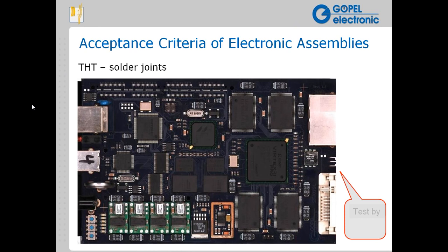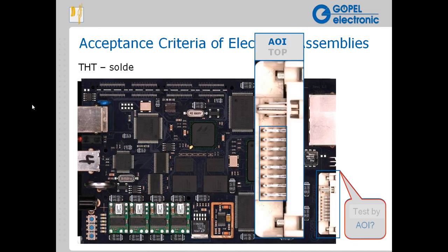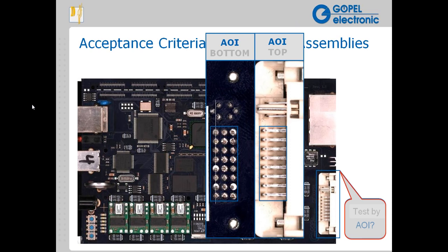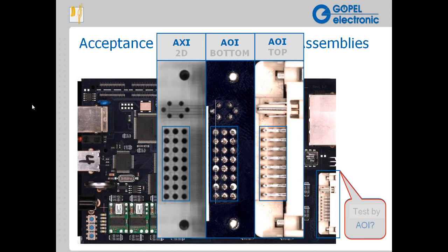As you can see here, we've got a 3D illustration of the solder in the through holes. If we take a look carefully, we can actually profile these particular solder joints at different levels in the Z aspect for the solder joint. And as you can see here, while this solder joint may look just fine on the surface, as we descend down through the hole, we can see issues.